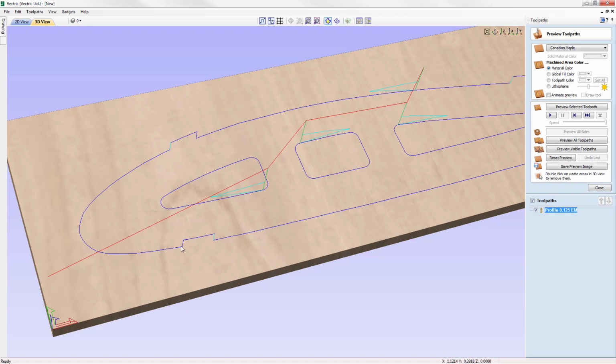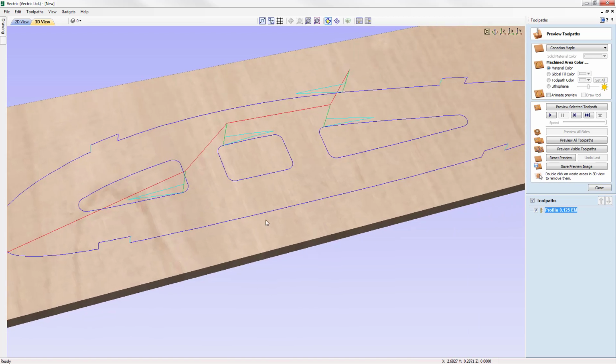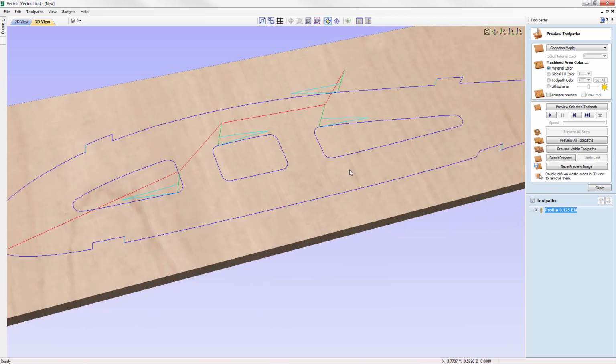And then wherever you see a dark blue line, that is the feed, so that's it actually cutting away into the material. You'll see these areas here, we've got these lifts, so this is just where the tool is making way for the tabs, so that's where the tabs are positioned, and this pretty much represents all of the moves that's going to be cut within this part.